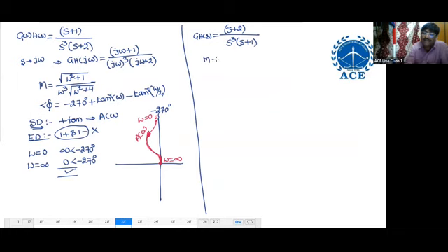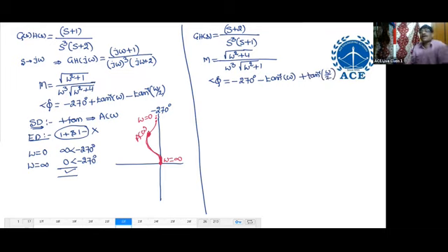Magnitude you tell. Root of omega square plus 4 by omega cube into root of omega square plus 1. Phase angle you tell. Minus 270 minus tan inverse omega plus tan inverse omega by 2. Same thing now. Don't draw the polar plots by using type and order like some textbooks.